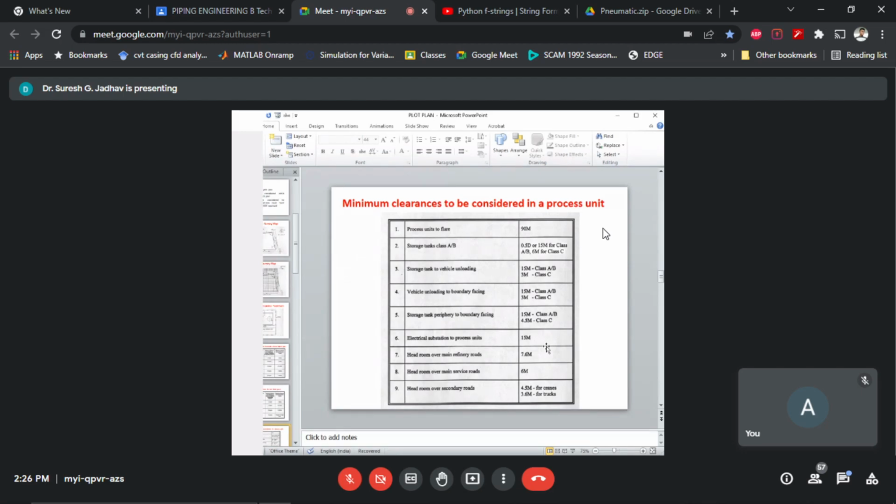We have to maintain the distance between vessels in one installation and distance from the building or group of buildings. The area where vessels, pumping equipment, loading and unloading facilities, and direct fired vaporizers are provided shall be enclosed by an industrial type fence at least 2 meters high along the perimeter of the safety zones, and minimum distance to be observed around the installation shall be as per the guidelines of regulatory authorities, which we have seen in the tabular forms, notwithstanding anything contained in sub rules above.